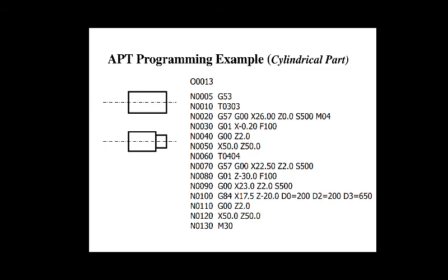Okay, and we have given some finish allowances in the X, Y, Z directions. In the X direction the allowance is 0.2 mm. Only X and Z are there, there is no Y. So in the Z direction we have also given a 0.2 mm allowance, and the depth of cut of each pass we have kept at 0.65 mm.